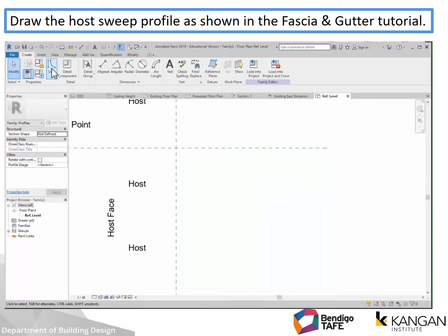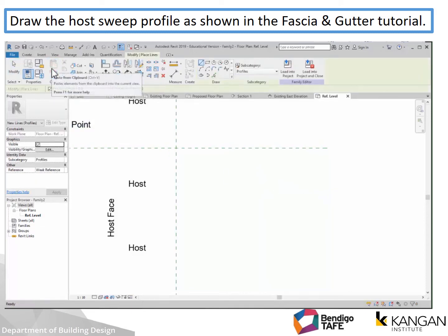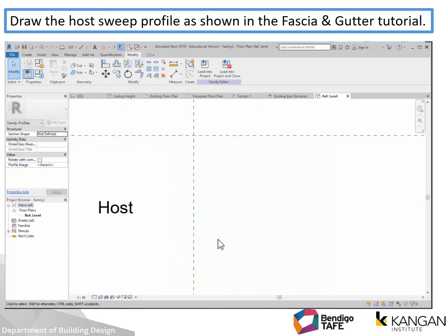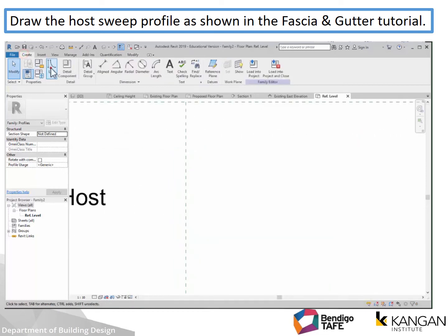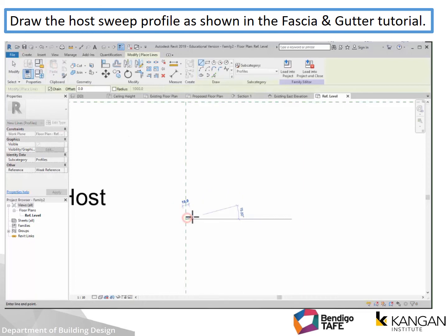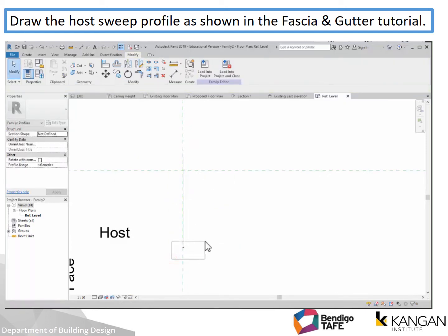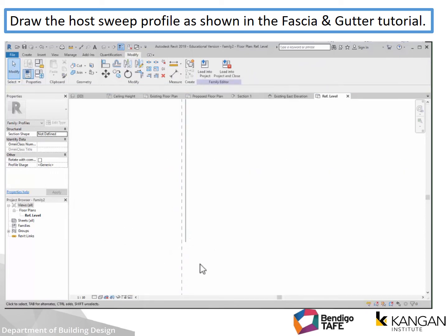So starting with a line command, what do we need to come off? 3mm. So I'm going to start on that line somewhere, type in 3, enter. I think it's a bit too far away for that to happen, so we'll try again. Create line, come out 3, and I'll just bring that line all the way straight up. I'm then going to go back and delete that 3mm line. Feel that's part of that diligence, making sure we're not leaving any trash line around that'll give us grief.